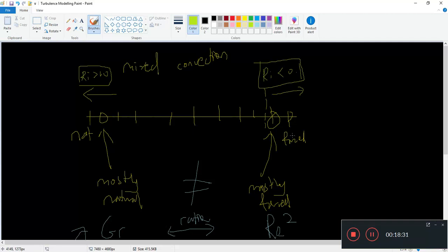When I say neglect, it is probably more to do with the velocity profiles. You would see later in the simulations that even a small bit of natural convection in a turbulent forced convection flow will severely change the heat transfer coefficient and even the skin friction coefficient.